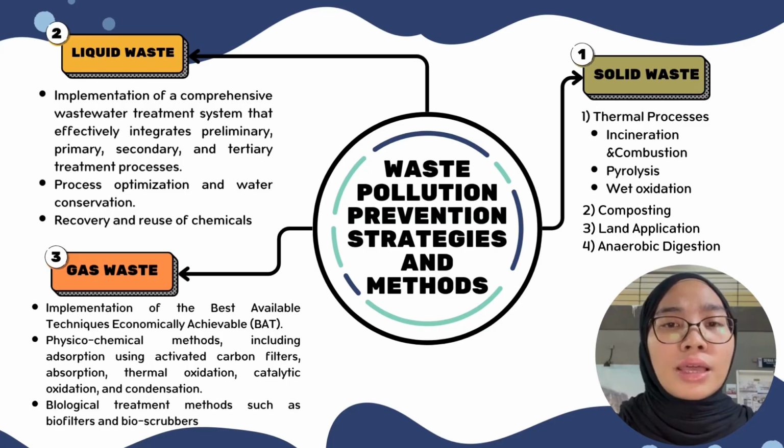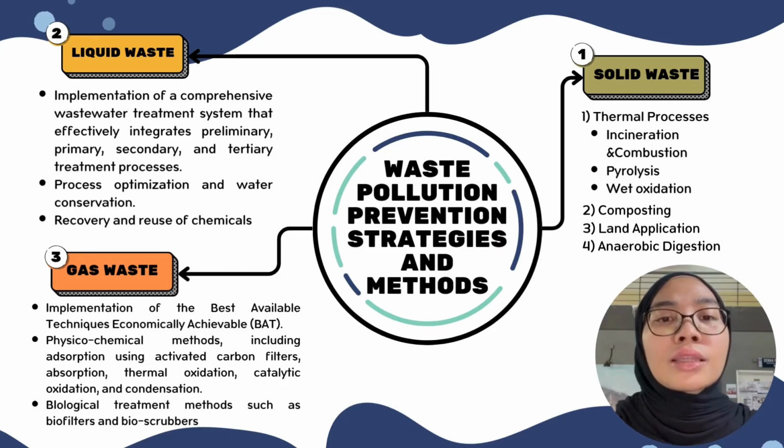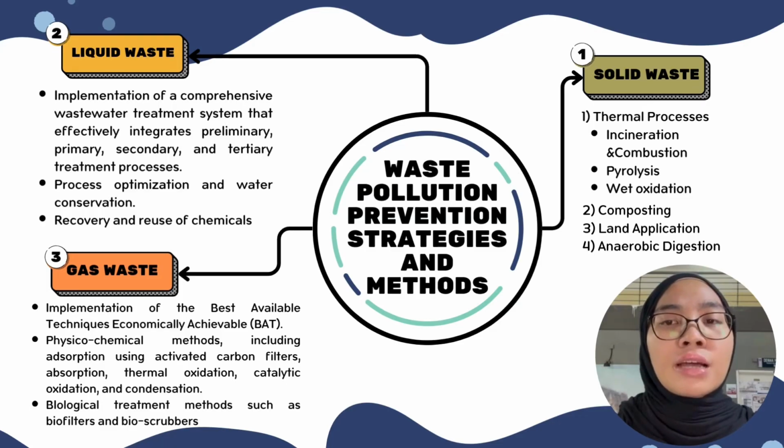In the aeration tank, microorganisms decompose waste with oxygen support. The activated sludge process forms sludge floc to capture contaminants, while the secondary clarifiers separate treated water from sludge. Tertiary treatment ensures the final effluent meets environmental standards. Filtration removes fine particles. Meanwhile, advanced oxidation breaks down pollutants, and disinfection via chlorination or UV eliminates pathogens.